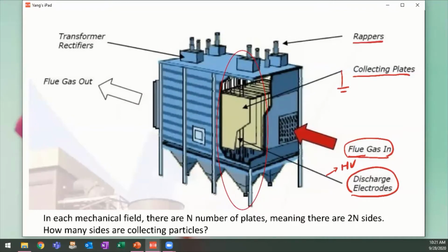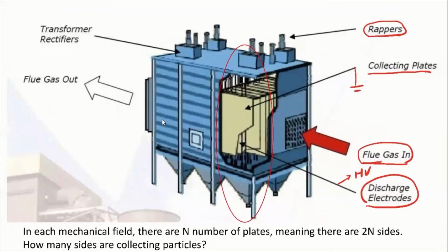And you see here are also some rappers. The use for that is basically to generate vibration. So after some time of operation, you can vibrate the plates here. Once you vibrate it, the collected particles can just fall down onto the collector here. Okay.